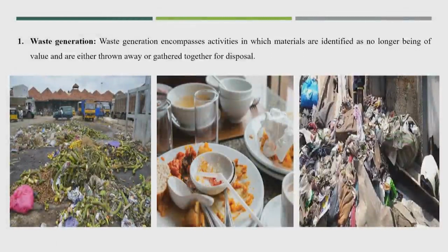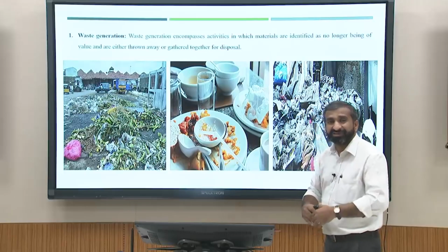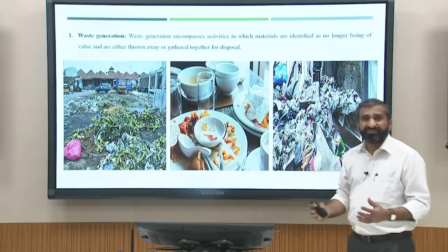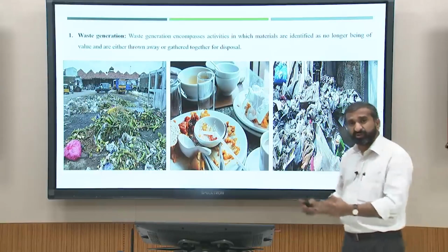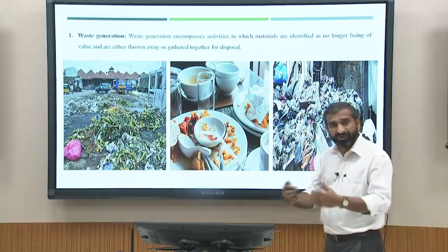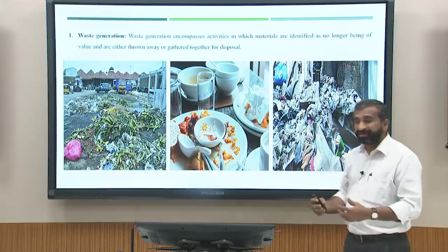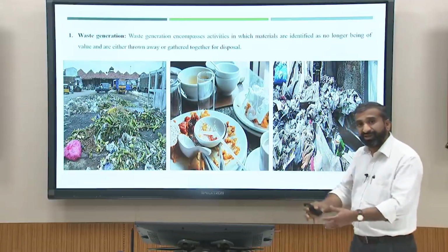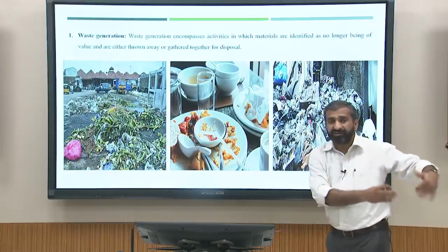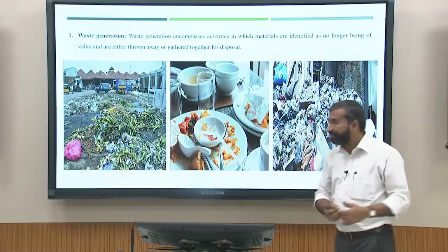Obviously, the collection system will be different for such waste, because it is normally biodegradable waste. Once it is stored for a longer period, it will produce odor and a lot of leachate. So, a lot of issues will be created from such waste. So, you should have the proper collection system and provide it for the biological treatment process.